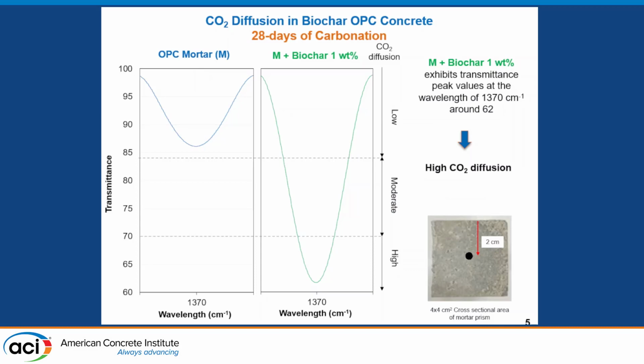Diffusion in concrete depends on the kinetics from the surface to the interior of concrete, obviously. And we assessed the FTIR spectra. We measured the transmittance at the center of the cross-sectional areas of our prisms, with approximately 2 centimeters from the surface.